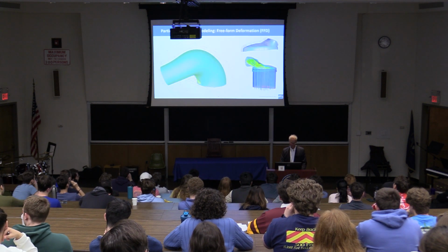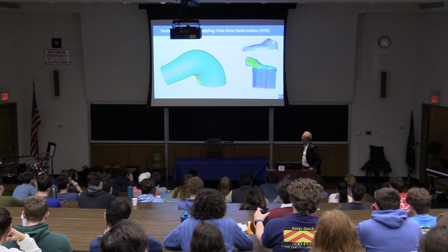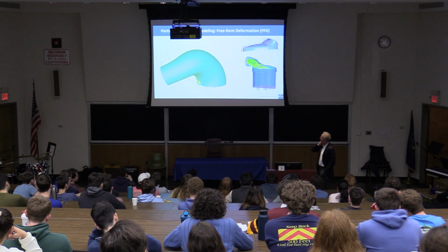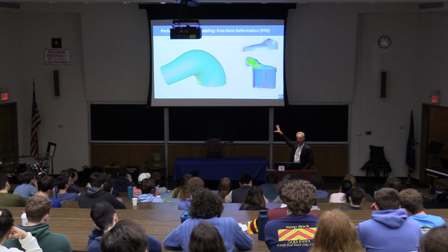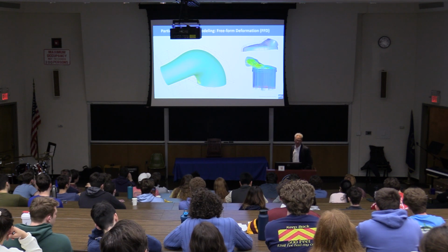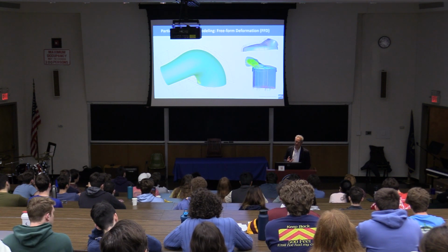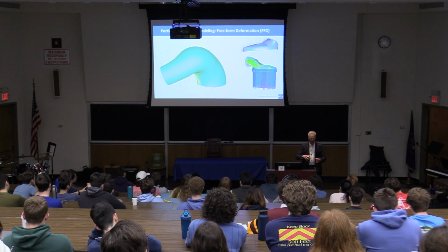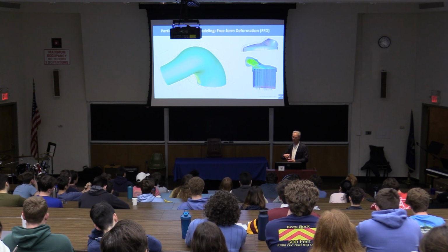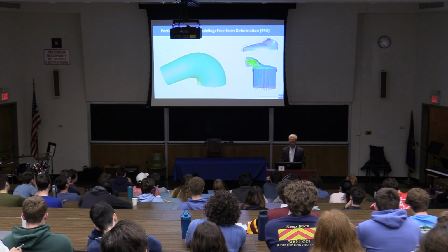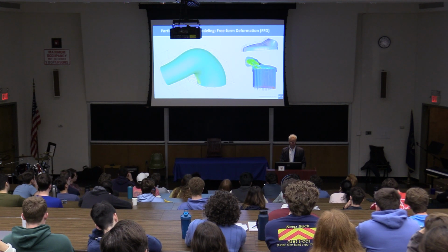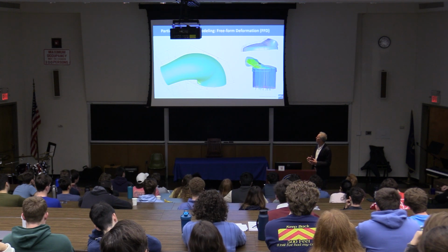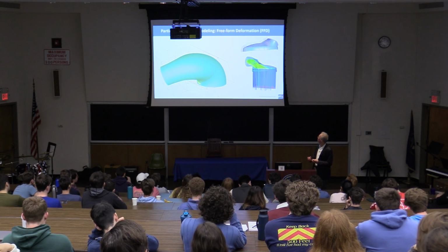Okay. Another example of partially parametric modeling is freeform deformation. It comes from the movie industry. You basically have a volume, a B-spline volume, and the B-spline volume has a lattice of vertices, and you can embed your geometry into this lattice and now modify certain vertices in your control volume, okay, and again, you might then just put certain vertices together so that you would control the geometry with very few free variables.